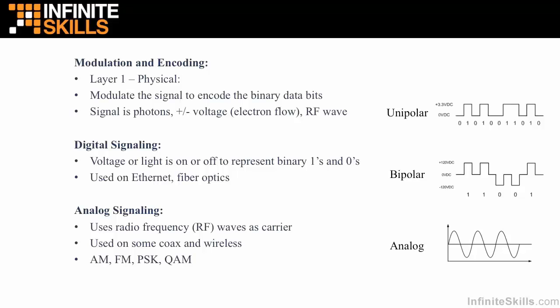Now, over a long distance, those binary 1s are going to attenuate. They're going to degrade. And over some distance, it's going to get to a point where the receiving side is struggling to figure out, was that a 1 or am I still at 0? I can't even tell. And so that's why we did this return to 0 for the definition of a 1 bit, and now that 1 bit is done. And here comes the second 1 bit, and now that 1 bit is done.